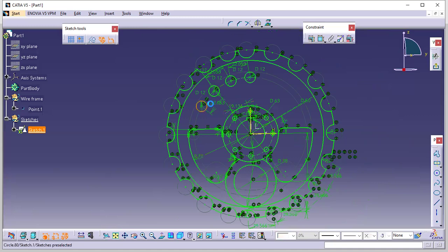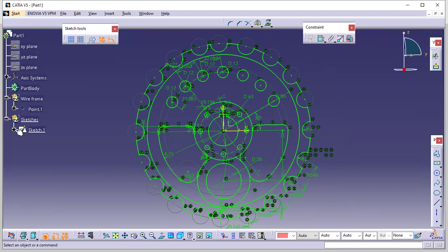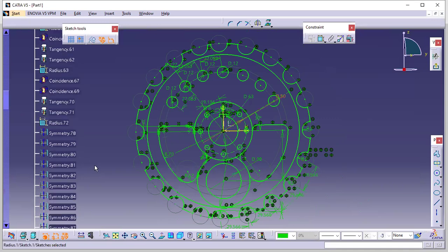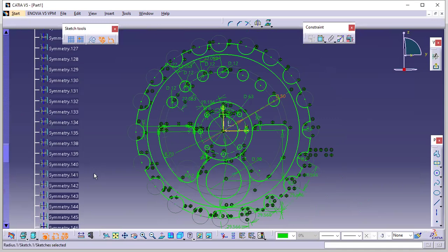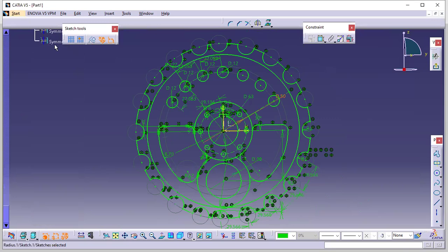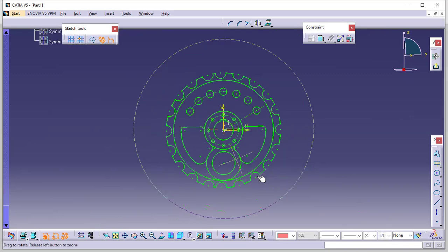So now what I do is I'm going to mirror this three to the other side. Yes. So you check now. So your sketch is finally iso constraint. In this way, you can do the sketching. If you want now, you can hide all the constraints from here. Just expand it from here to here last. So hold the shift button, select here, and you can hide it. Your sketch is ready.